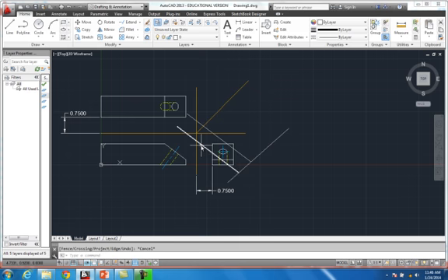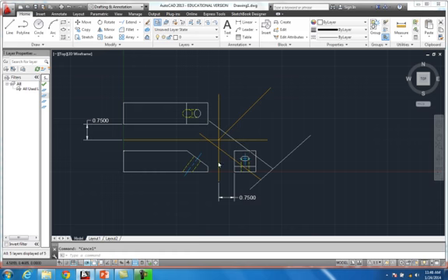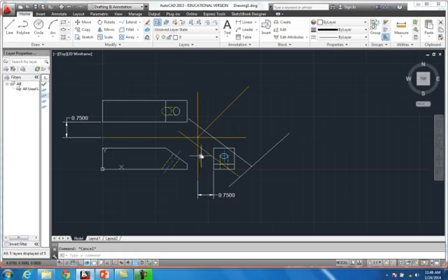Of course, this was my fold plane. I'm going to come up here and change that to my folding line. Just like that. And this is what I do. I go up, and according to the fold line method, what you have to do is kind of an old school method. Just go up here and hit linear, catch that to that, and it's 1.75, that distance.